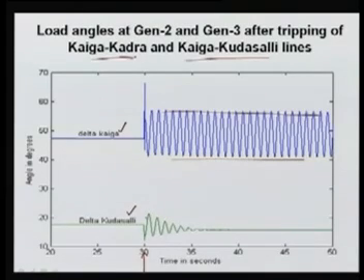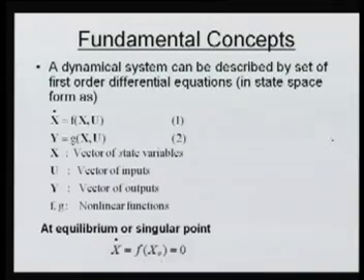So here it is damped out, no doubt, but this is a persisting oscillation and that is not required, that is not good, especially for a nuclear power station. So it is found that there is some dynamic stability issue in the power system, they keep on oscillating, and then we should go for proper damping or proper measurement as well as proper mitigation techniques for these dynamic oscillations.